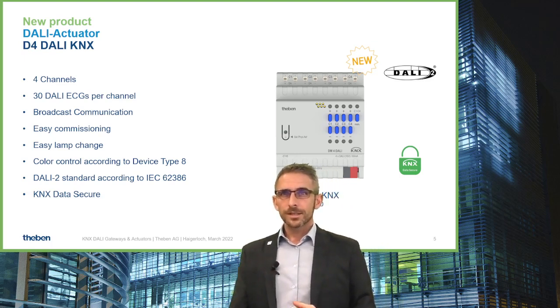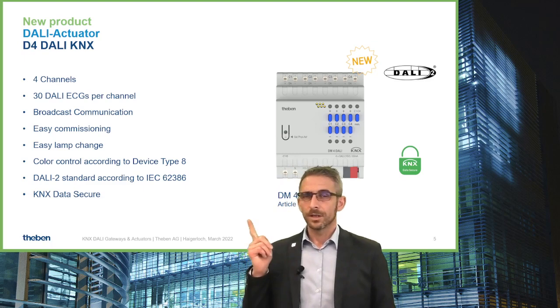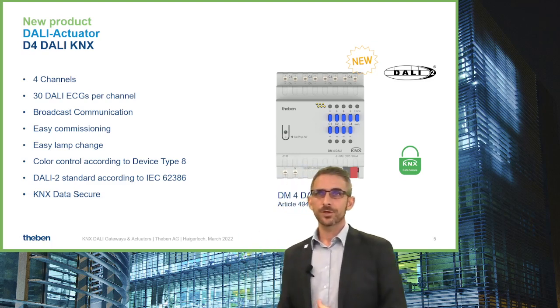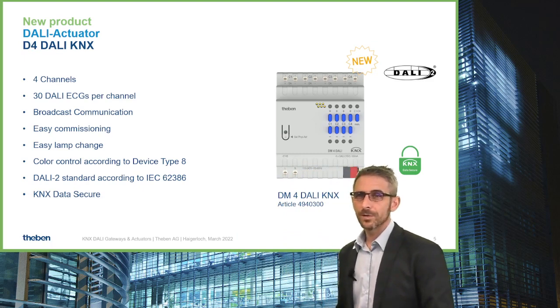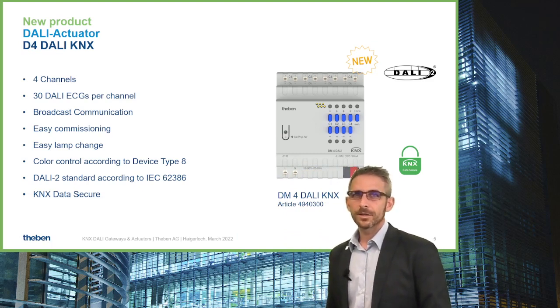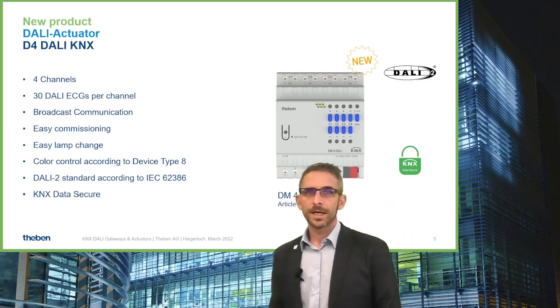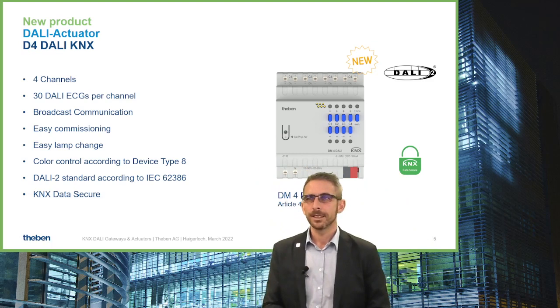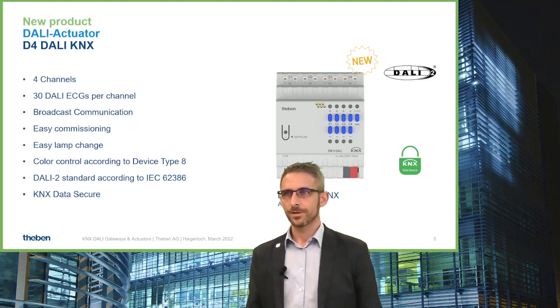Included with this DALI actuator we have color control, so we can control color and color temperature according to DALI Device Type 8, and it's a DALI 2 certified device, and we have included a secure communication following the KNX Data Secure standard.